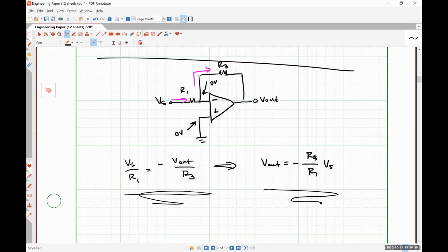And if you can memorize all of them, you can actually get away with solving an awful lot of op-amp circuits with doing zero circuit analysis whatsoever because they're very well behaved. That being said, you can still just find the voltage at the non-inverting input terminal and then apply KCL at the inverting input terminal and not have to memorize 6 different types of op-amp circuits. So it's really whichever way feels more comfortable to you. I'm not trying to discourage anybody from memorizing the different topologies, but the method that we talked about today is, in my opinion, pretty darn easy.